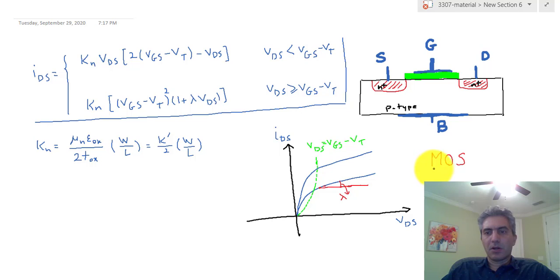The reason that they're called a MOS, or metal oxide semiconductor, comes from the physical operation of the device and how it's actually fabricated. This is a simplified cross-section of the device. This is a silicon substrate, or your semiconductor substrate, right here. Usually silicon, and the silicon could be lightly doped with boron or phosphorus, or n-type dopants.